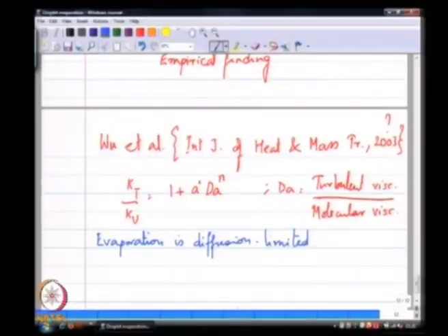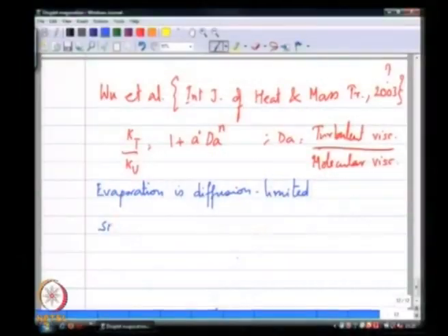So, this ratio of the turbulent diffusivity or viscosity to the molecular viscosity or diffusivity is another parameter that accelerates this diffusion process, and therefore, the d squared law rate constant has to be modified for the presence of turbulent diffusivity in the process. Now, these are all still single droplet level phenomena.